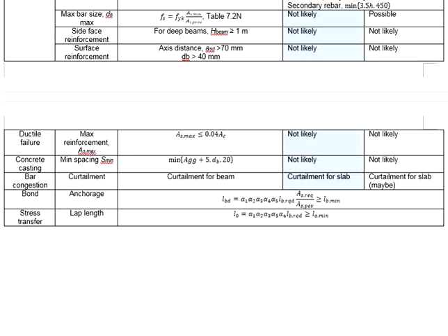As for the staircase, I am not aware of any rules of curtailments at the moment. Probably the rules of curtailments of the slab would be applicable. Now, if you are not confident, probably you just don't do the curtailment. This can lead to slightly higher consumptions of the materials used in this staircase.